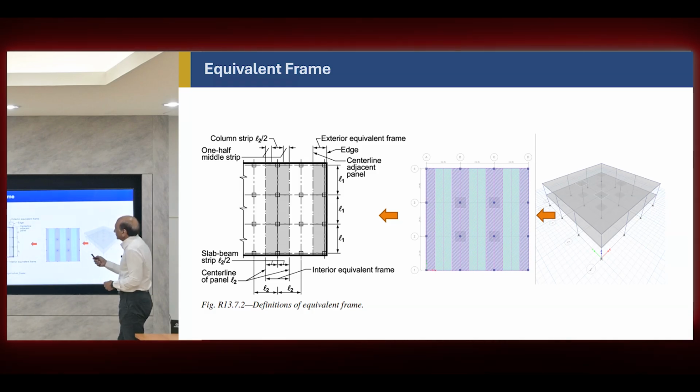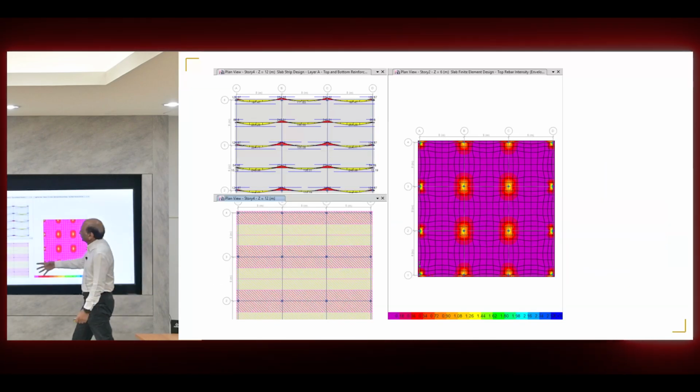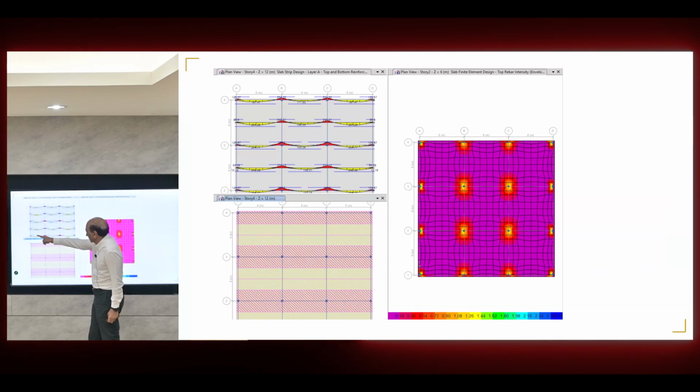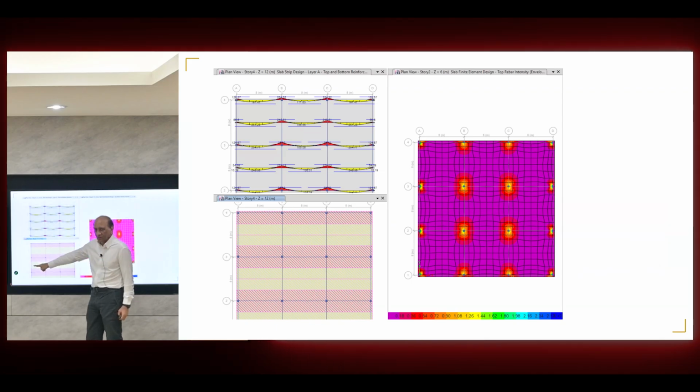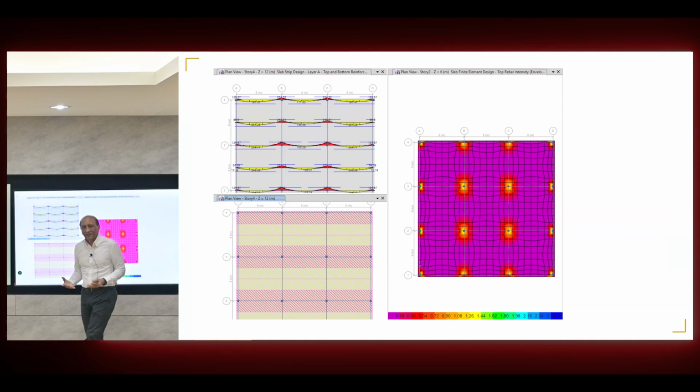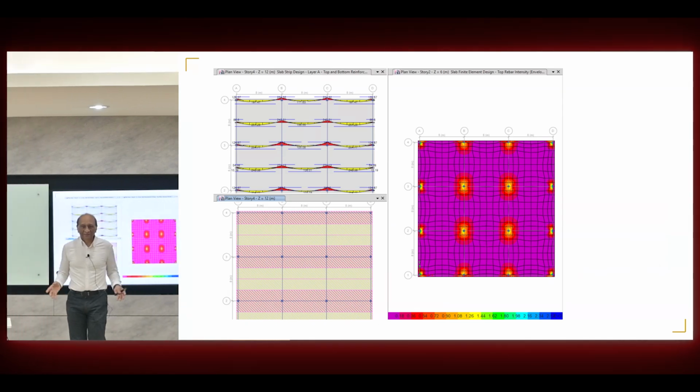Okay. And then you take that strip, you calculate the total moment on that, and then you calculate negative moment, positive moment, because it's a one-way thing in this direction. Now, forget about the other side. That we will deal with independently, because we already established that the two directions are independent. Each direction will carry 100% of the load.